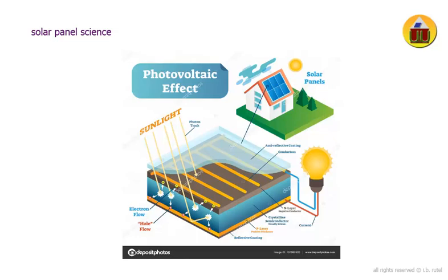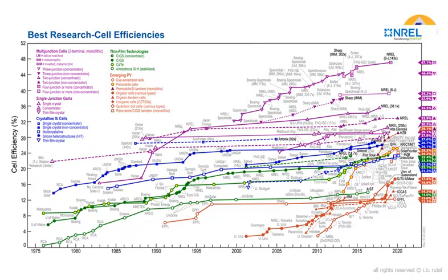How much electricity is produced is a function of the material the solar panels are made from, the amount of light the panels are exposed to, and the efficiency of all the components in the solar panel system. Also, the temperature of the panels, and several other considerations. Current research for solar materials tends to focus on the efficiency of electrical production in just the solar panels themselves, where recent advances can provide a conversion of almost 50% of the light hitting the panels being transformed into electricity. Unfortunately, the commercial efficiencies don't reach nearly that level, as we will see.